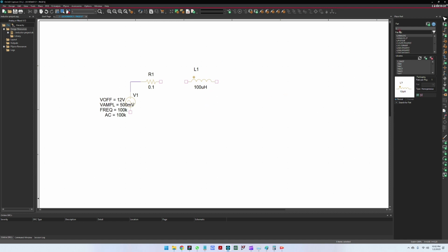Okay, and for the purposes of seeing how this works in a circuit, we will need a load. So let's place a resistive load. The resistor appears when you press R. Here it's R analog from the component library.